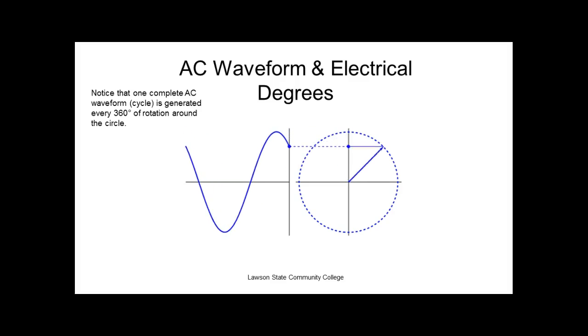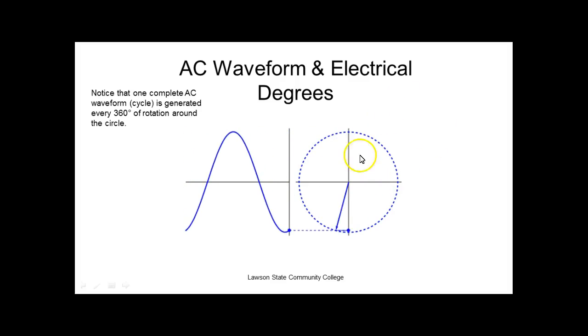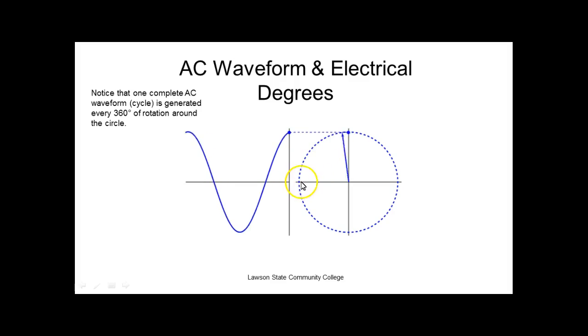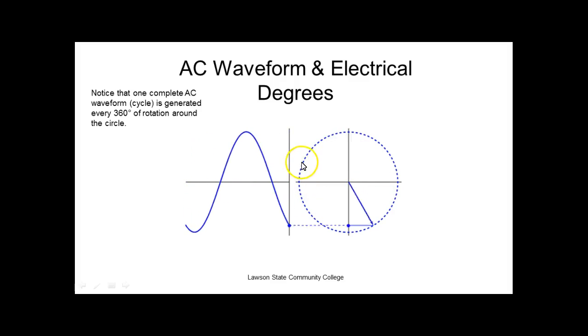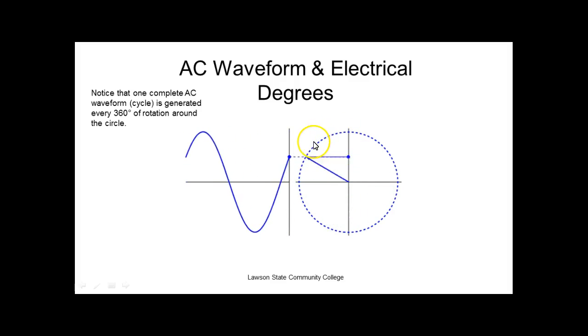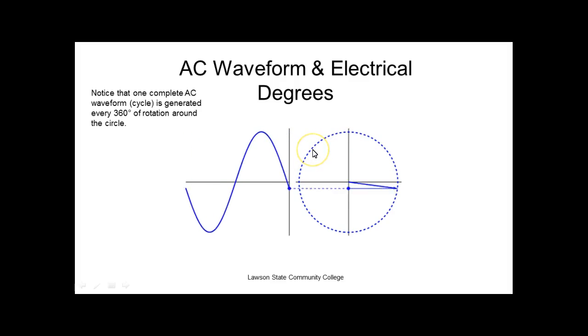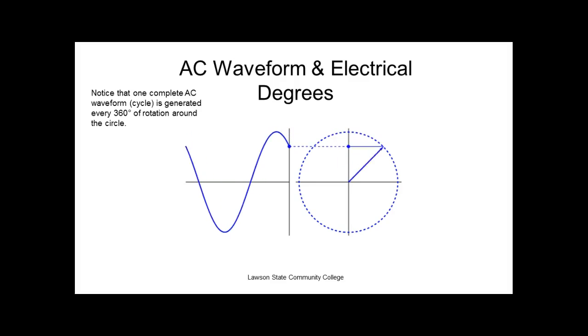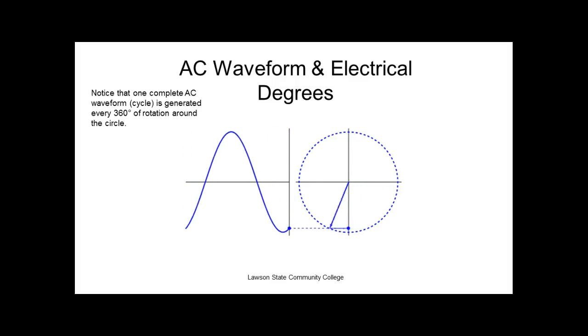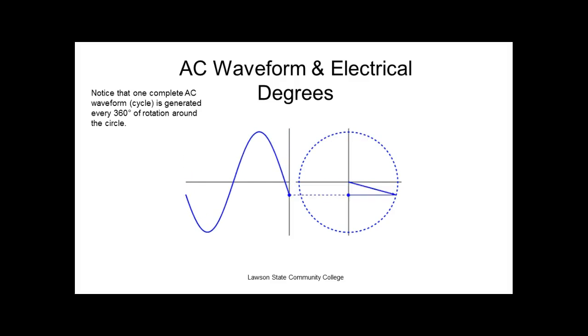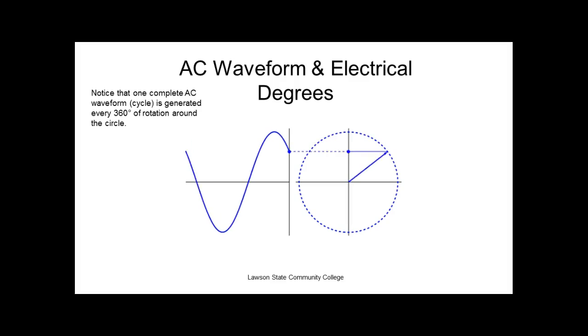A lot of people say, well, if 90 degrees is maximum, and this right here is 0, and this is 10 volts, what would it be at 45 degrees? A lot of people would say 4.5 volts, but it's not linear, right? You understand that? It starts off almost like this, and then as it approaches peak, it starts doing what? Levels off. So 50% actually occurs at 30 degrees.